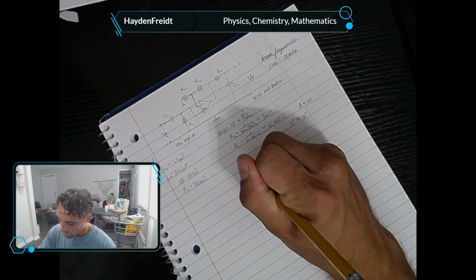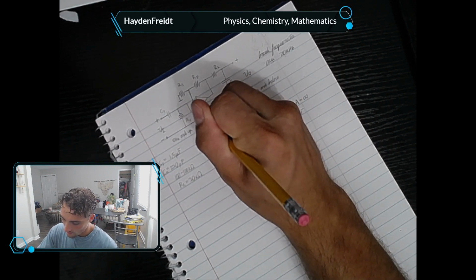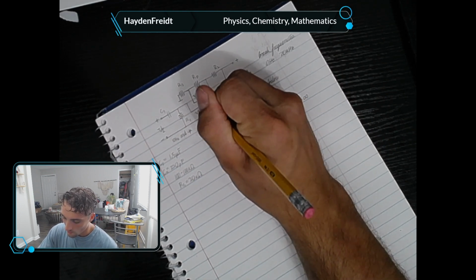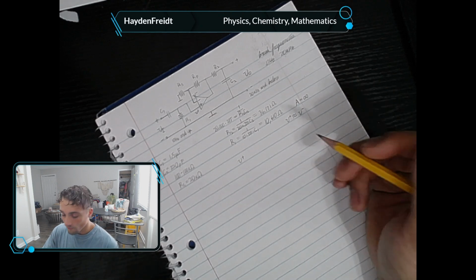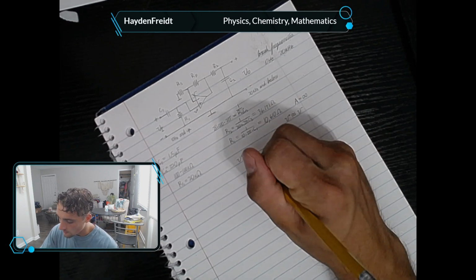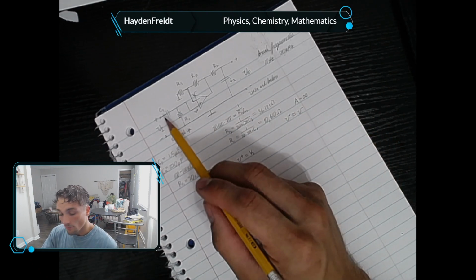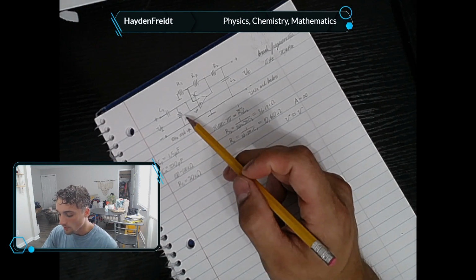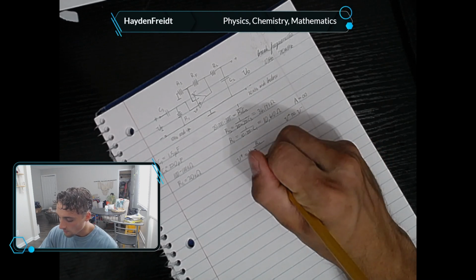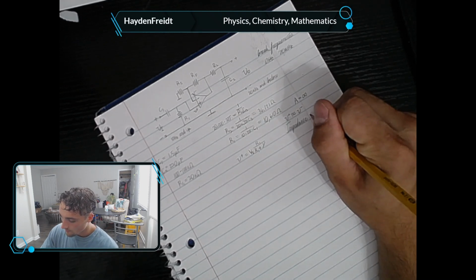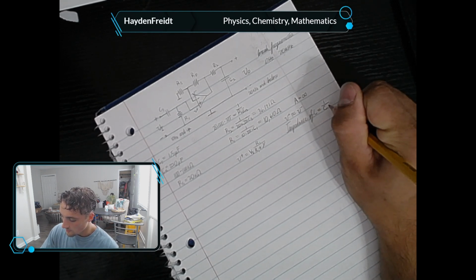The voltage divider relationship is going to look like this. Let's define this as V positive and this as V negative, also known as the non-inverting input and the inverting input of our operational amplifier. V positive is going to equal VI multiplied by, looking at these components in series, we're taking the output of the voltage across R1, so R1 is in the numerator, and then the sum of R1 and the impedance of C, which equals 1 over C times S.